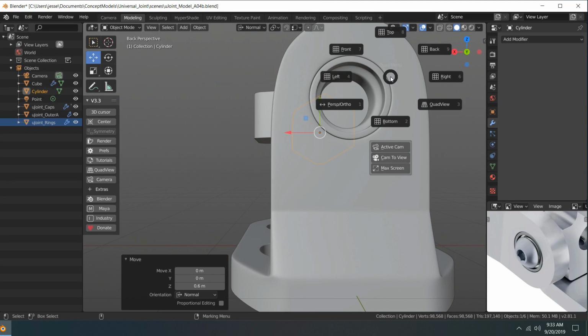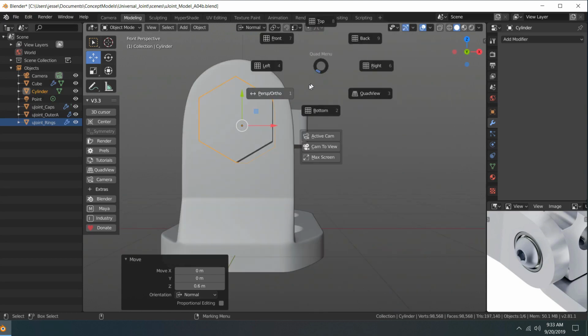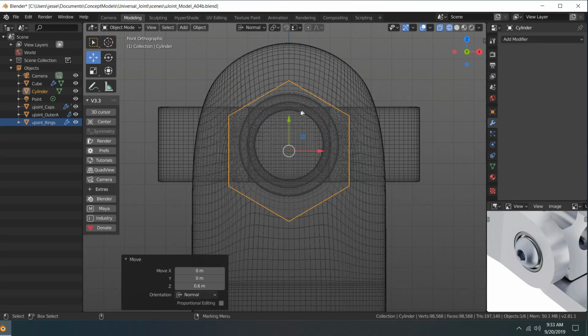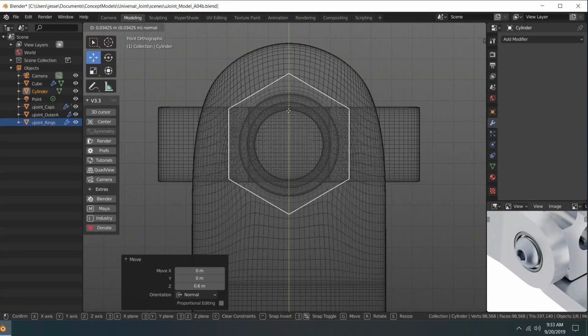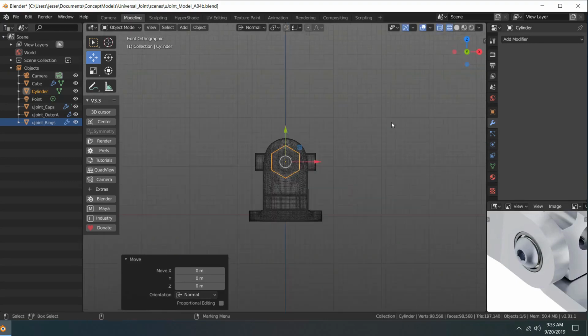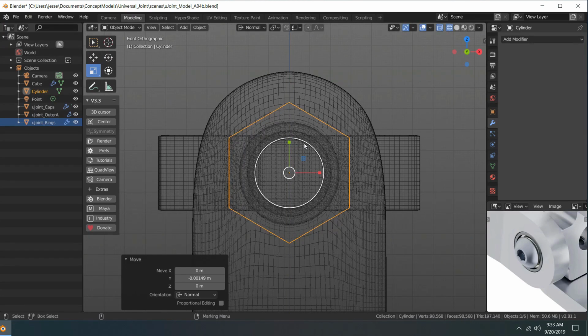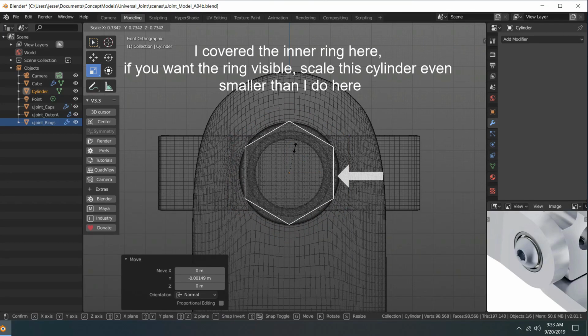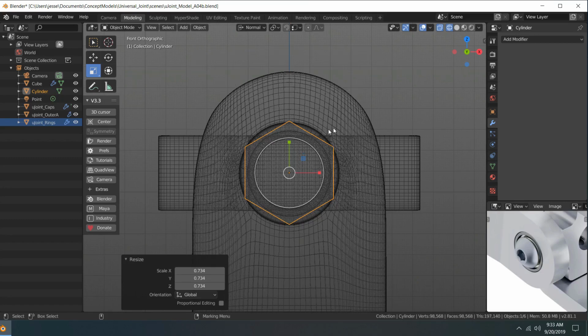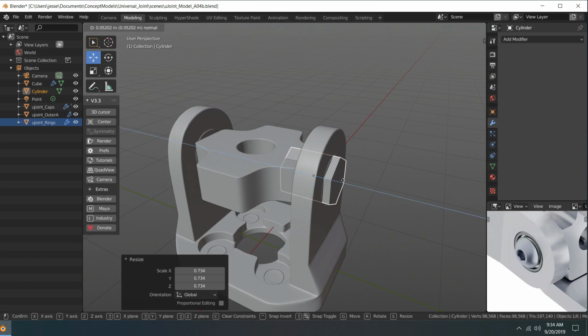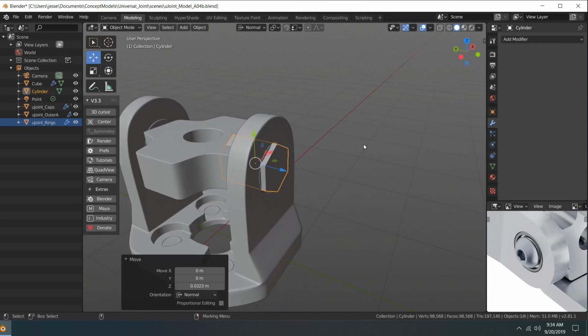I can actually go into, let's see, I think it would be front view maybe, orthographic, front view, and we can turn on wireframe up here. Okay, and we can just move and scale it into place. So something like that, we'll finesse it a little bit later for sizing. And then back out into perspective. We'll put shade smooth back on here, and I'm just going to move it out a little bit. So we'll say right there, and let's isolate select by hitting Alt-E.